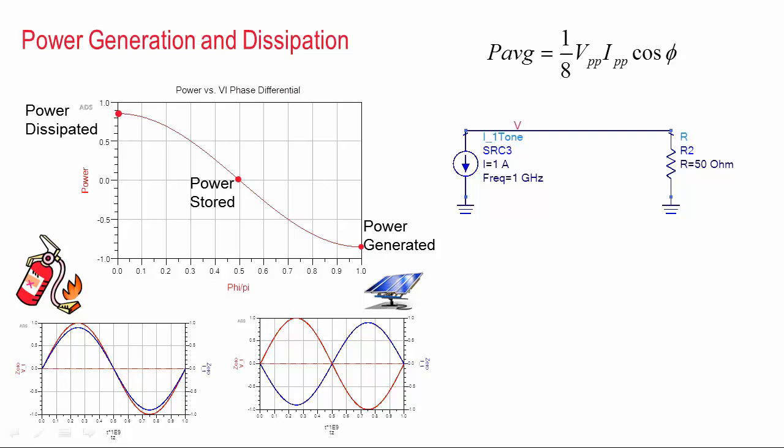So here's an example of a circuit that we're going to use a lot in power amplifier design. This is an AC current source which is tied to a resistor. And since these components are connected in parallel, the current source and the resistor share the same voltage across them. But since the current source pulls current out of the resistor, the currents are opposite in the two components.